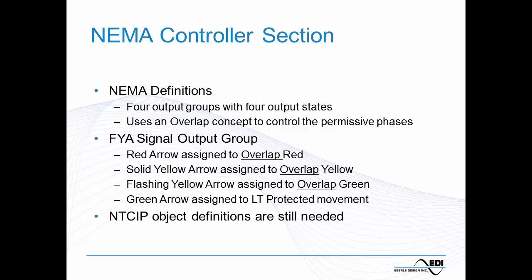Now at this point, NTCIP object definitions for programming a controller for flashing yellow arrow operation are not yet defined, but that's going to be something that will appear likely in the controller ASC object definitions at a future date. So keep that in mind as well as you deploy this.